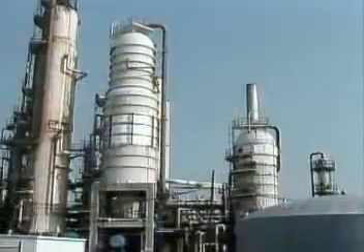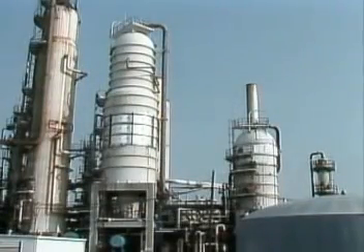When the pressure inside a tower is reduced, liquids are vaporized at lower temperatures. This process is referred to as vacuum distillation. Now, keep in mind that a vacuum tower does not operate under a perfect vacuum. Vacuum distillation simply means that the pressure in the tower is lower than atmospheric pressure. Vacuum distillation is used for several reasons.